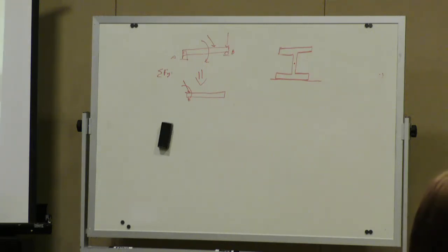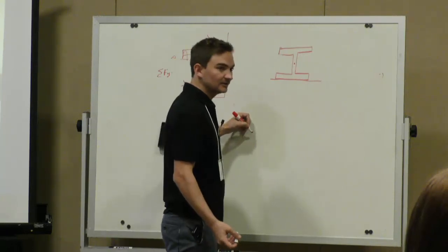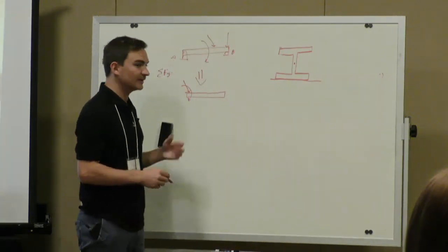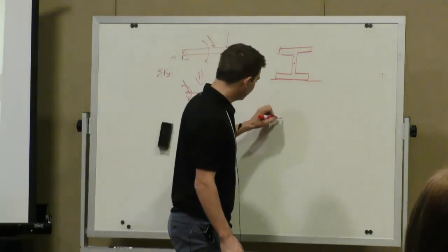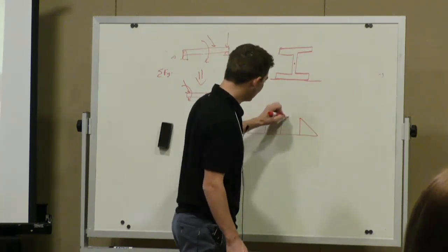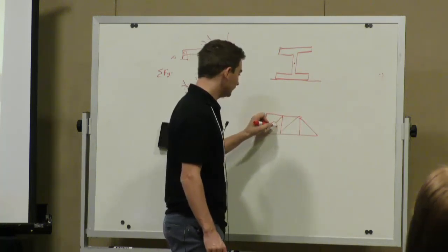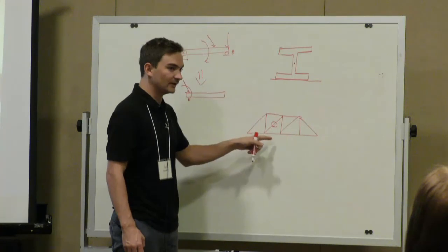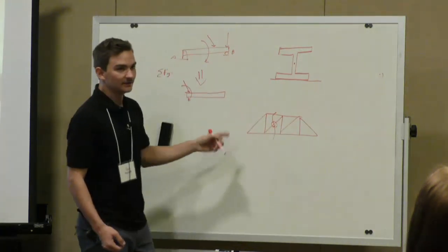Then I guess the last thing that I can think of would be a truss, solving a truss using either method of joints or method of sections. Because if you have a system and every connection is pin connected, and it asks you to find the force in a certain member, you don't want to solve by method of joints, slowly going through. You might want to just take a section cut and solve for it then.